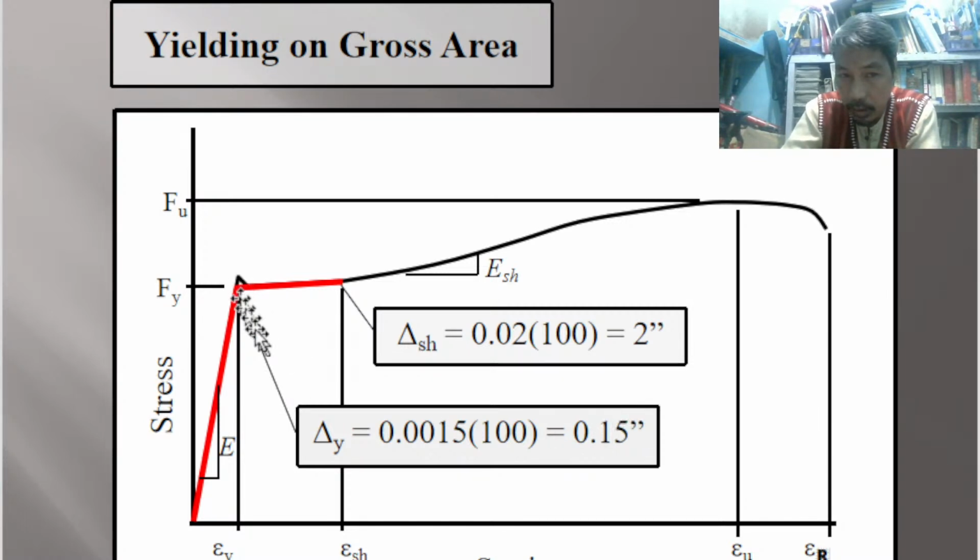And that is on the yield point. So this point is again 0.001 to 0.002. This is from 0.01 to 0.03, and the ultimate strain is from 0.1 to 0.2, and the rupture 0.2 to 0.3. So remember, recall that diagram. Okay, the common values.